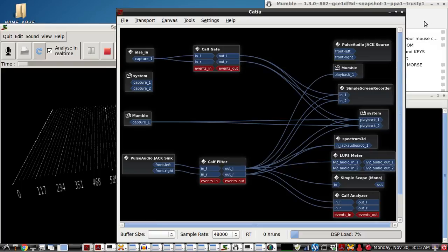So we have the paddles hooked to the serial port pins. In the show notes, there's a link to a PDF here where it shows you which pins to use. And I just have a very cheap USB to serial port adapter. I've actually just got clip leads connecting to the 3 leads of my paddles. One to ground, and then one to the DTR, the other to the CTS pin and DSR pin. So I think those are the 3 pins we're using.